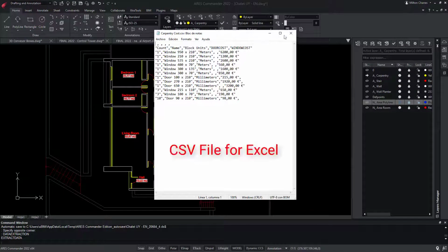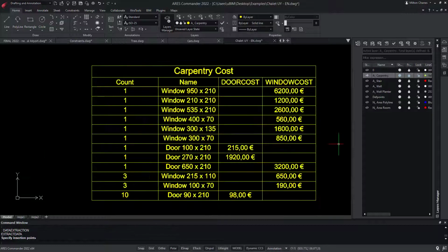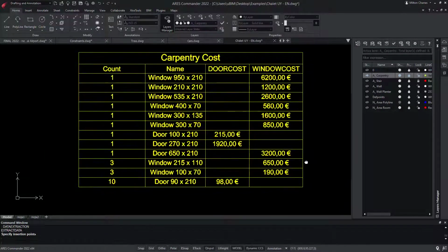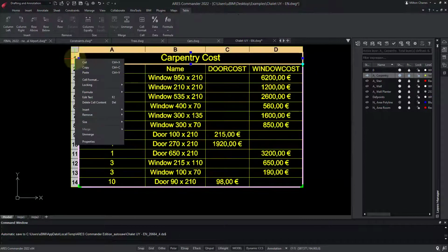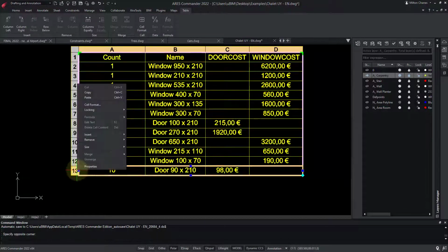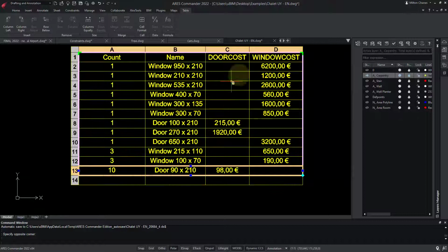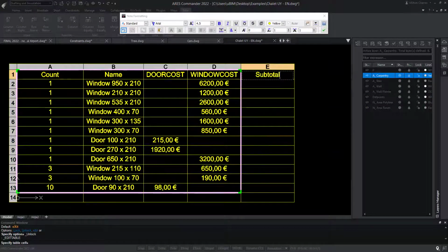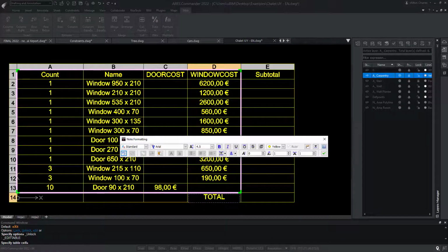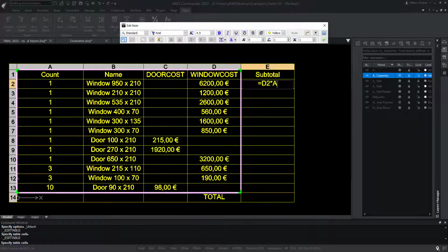The same feature can also extract the data into a table. We see this table is listing the quantities for some blocks and showing their attributes. As this is a table, I can add or remove columns. Next, I can add a formula and use this to calculate my costs without needing to go to Excel.